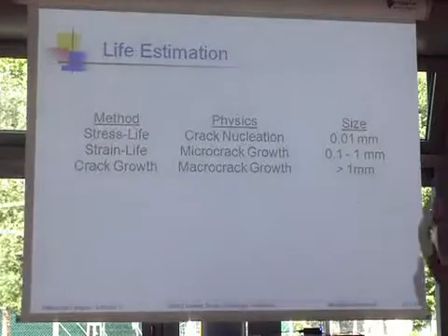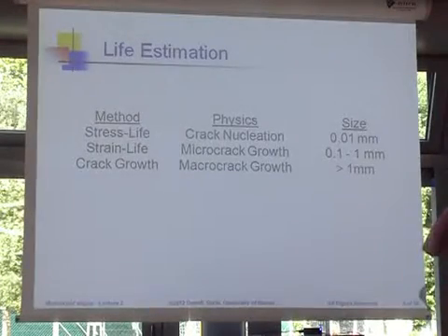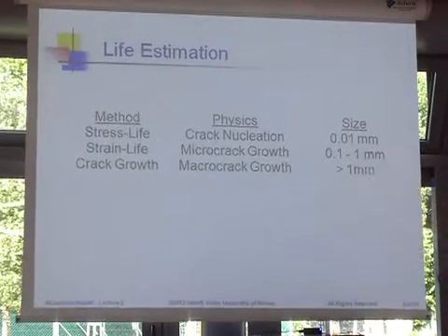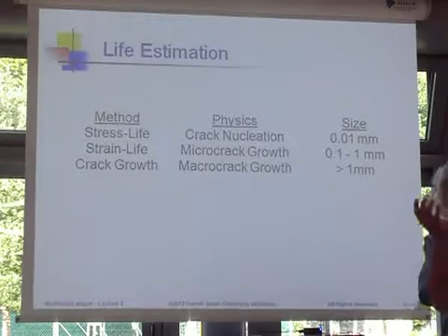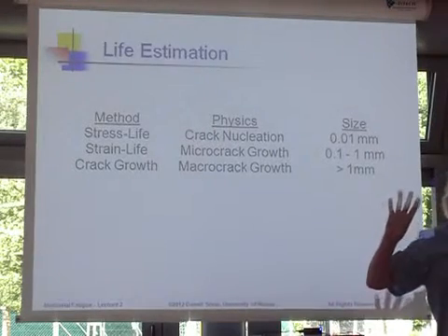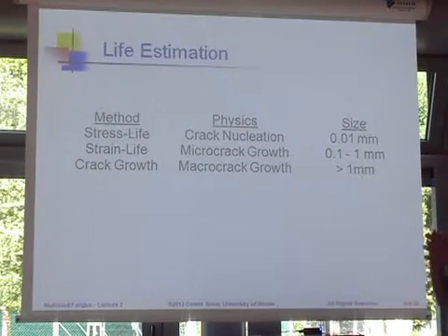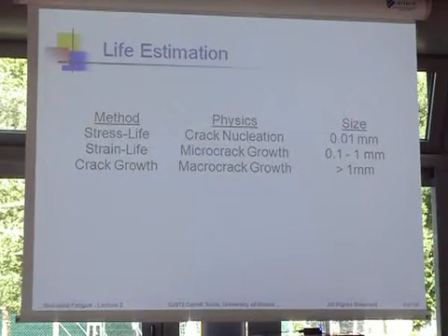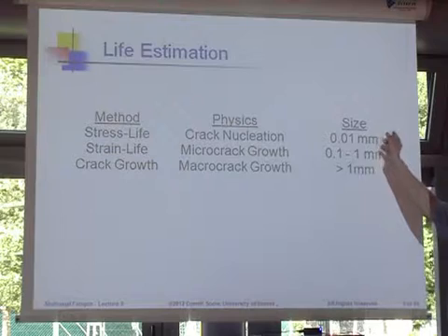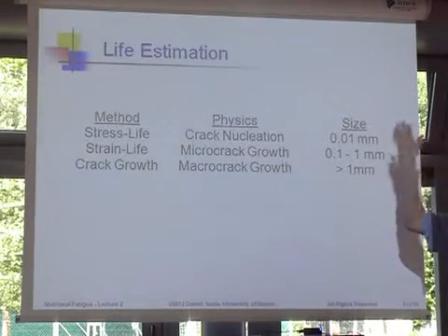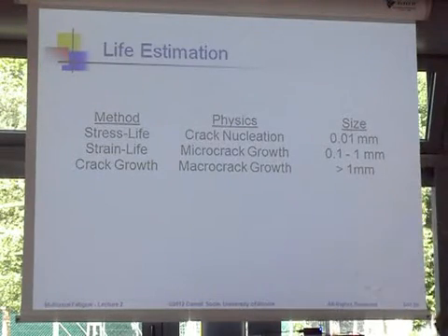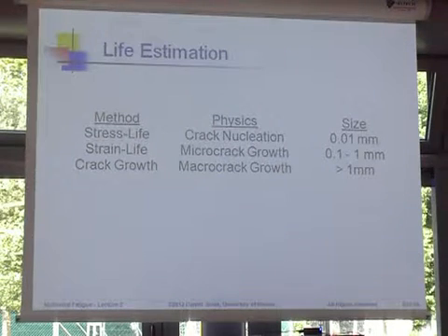So I try to tie these approaches a little bit to the physics. And so if my approach is to look at doing everything with stress life, the physics I'm really trying to model is crack nucleation, because I say this is the dominant part of the physics. Right? Majority of the lifetime is spent here. And that means on a size scale, that's something maybe 10 or 100 microns in size. By the time a crack gets to be 100 microns, it's certainly nucleated and it certainly will grow.